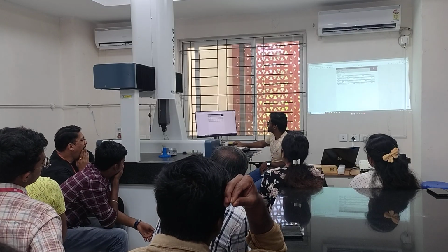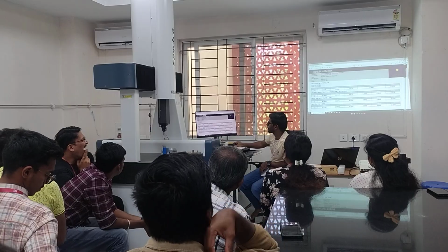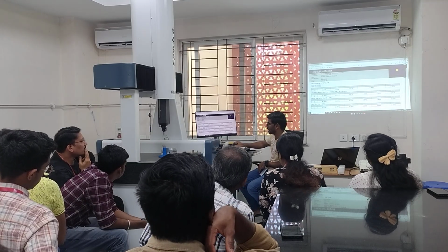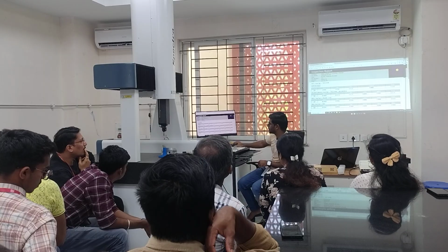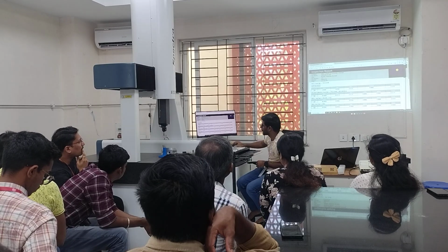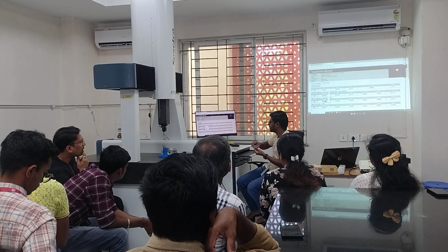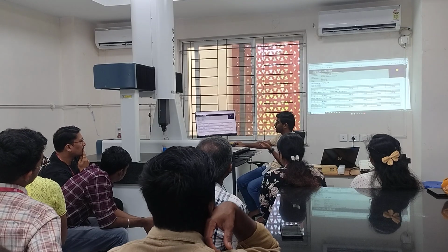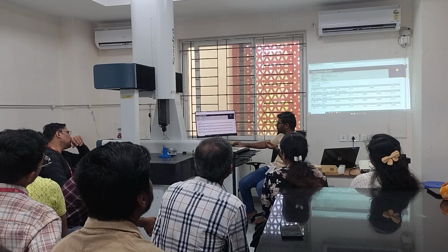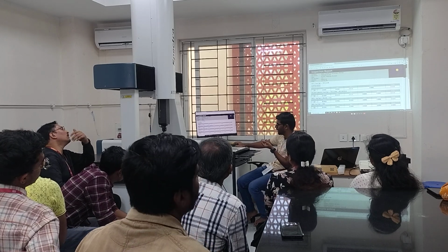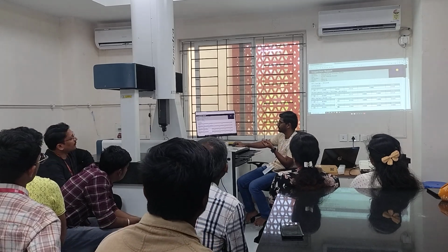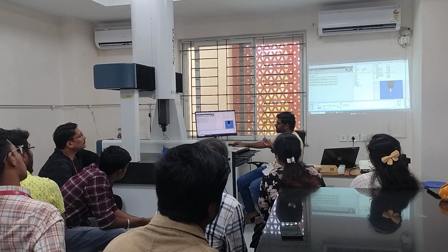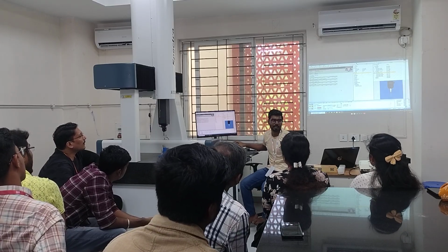Okay. So this is how the basic measurement is done. Flatness, I have got. The inclination angle, I have got. The dimension between them, and then I have got the circularity, the diameter of it. Diameter is this much. And this one I can compare with. Actually, it should be, I forgot to mention it, 25. So I must mention it here in the software itself. It is 25. Okay? Is this clear?